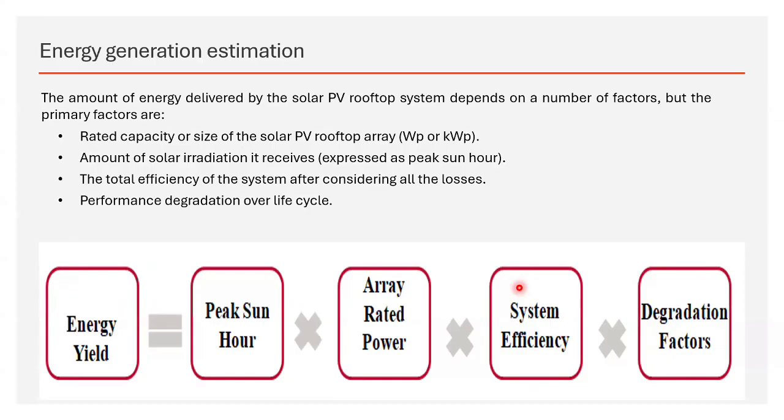So combining all this, multiplying all this, we get the system efficiency. And normally you will not get more than 20 to 30%, 25% is at very high end. We install a system that is 5 kilowatt peak, but if 5 kilowatt is generated throughout 24 hours, then 120 kilowatt hours should be the yield. But it is not like that. We will be getting 20% of 120 kilowatt hours, that is the net yield. So that's why the other popular term for this is plant load factor or the load factor. So we get only 20 to 25% depending upon the system design.